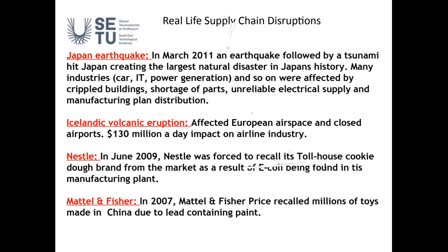And he called him over to a specific area in the warehouse and said, bring the forklift over with you. So he went over with the forklift, and the proper way of traveling with the forklift is the forks are down low and tilted. Got to where the manager was and he tilted the forks forward, flat on the ground for safety.